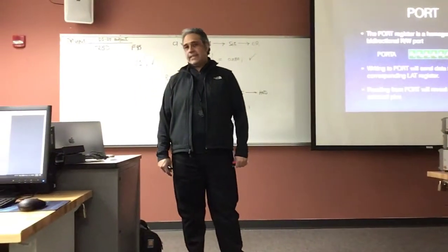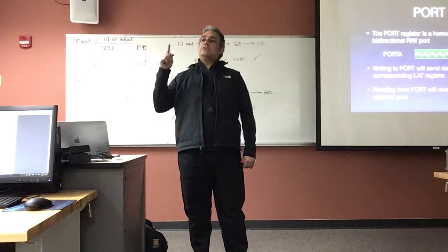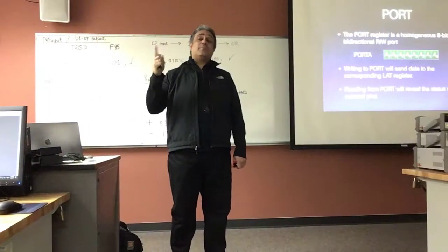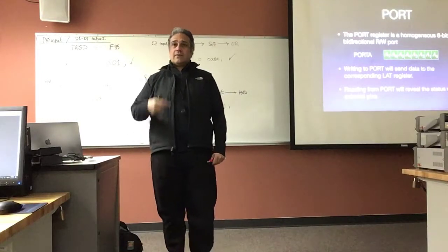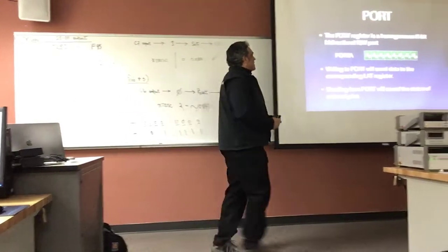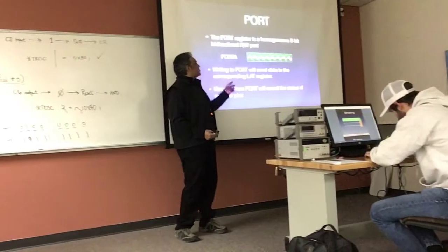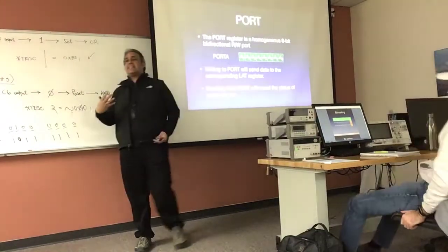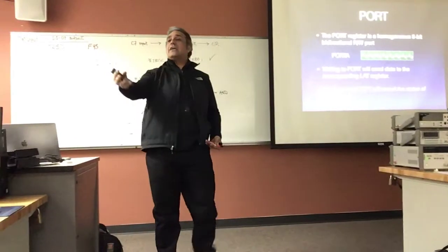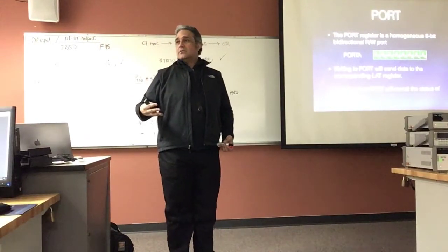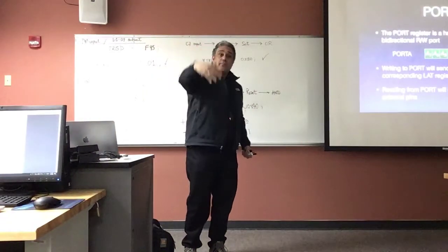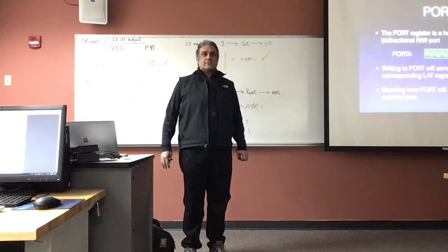Now, having said that, this is only true if the tri-state device has been set up properly. Okay? If I make my tri-state device an output and I try to read from it, you're not reading anything other than the last value that you latched in. Right? So your tri-state device determines the behavior of the port in some sense. Does that make sense? All right, good.